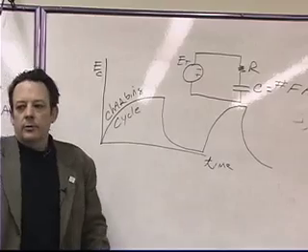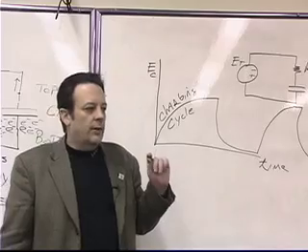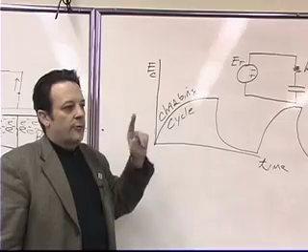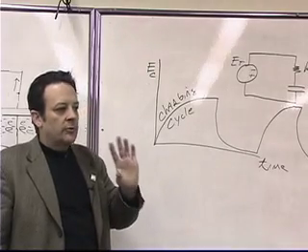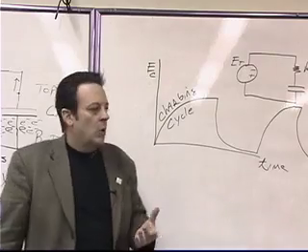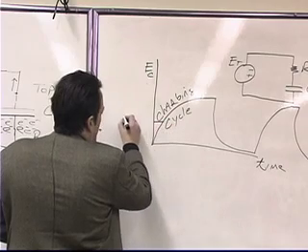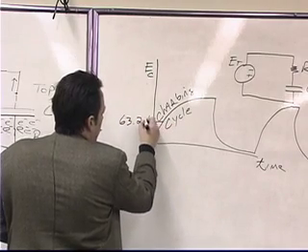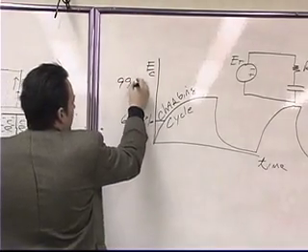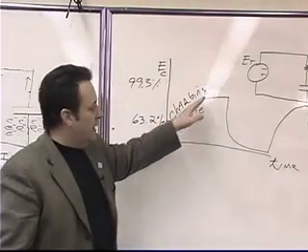Now, you might ask, so what? Okay, who cares? Well, one of the things that is really convenient about this and the fact that it always conforms to the same equation, even though it's an equation that we're not real familiar with, we can always predict when the voltage is going to be 63.2%, or when it's going to be 99.3%, or when it's going to be any value between those two.